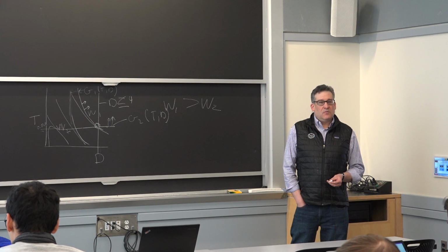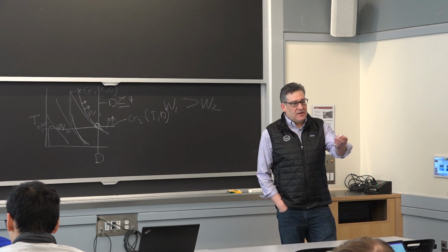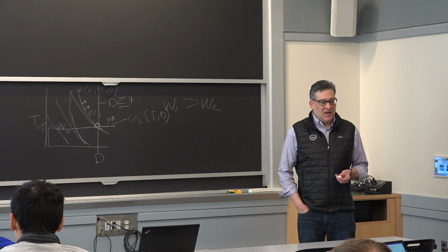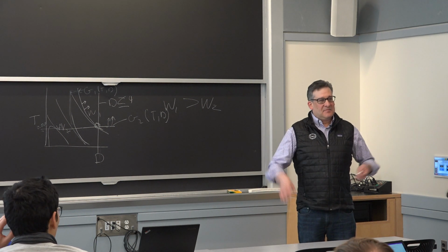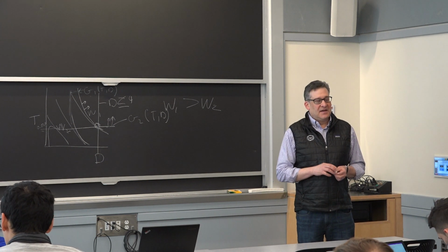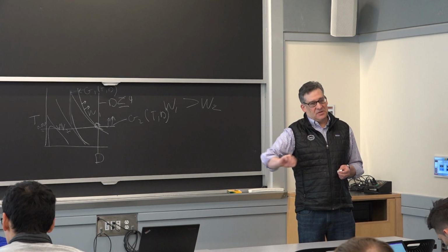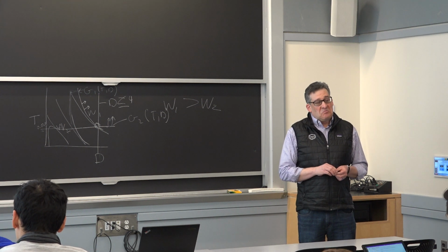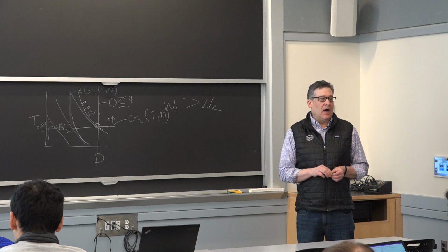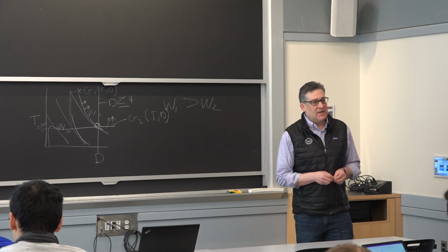Exactly. When you buy material, when you buy a Columbus tube from Columbus in Italy, you'll get a spec sheet with it. You'll get a cert, and they're claiming that they did mass spec or X-ray diffraction or something, and they figured out the composition, and this is what it is, and we tested the material, and these are the strengths we got. And most of the time they're right. Most of the time the values are what they claim or higher. Every now and then you get a batch of material that isn't.